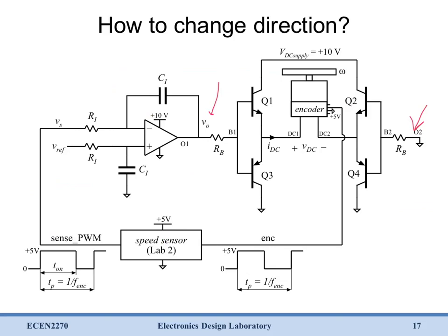Now, we're going to do that by driving this input here to 0 so that we can then vary this input. We want one of these at 0 at all times. So how are we going to drive this to 0? Well, we can do this just by fooling our integral compensator.